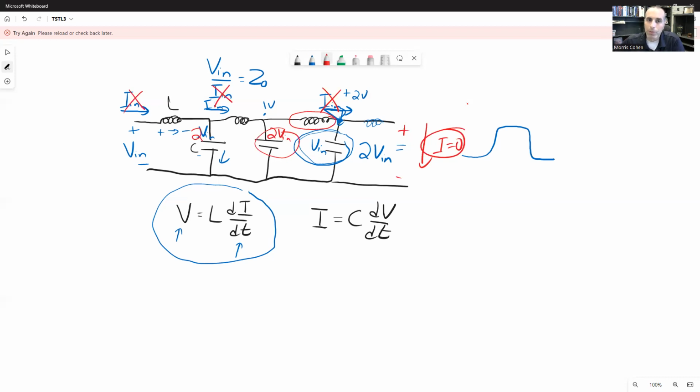Now, in terms of characterizing this voltage reflection, we're going to establish something called the reflection coefficient. Right? So we had 1 volt coming in, and coming backwards, we had a V reflected. I'm going to call this V out, which was also 1 volt. So we're going to define something called gamma. Capital gamma, this is very important. We're going to be seeing a lot of this. This is called the reflection coefficient.